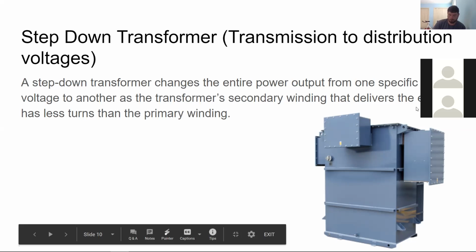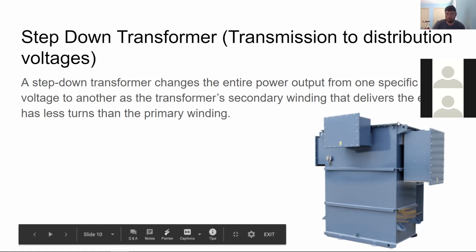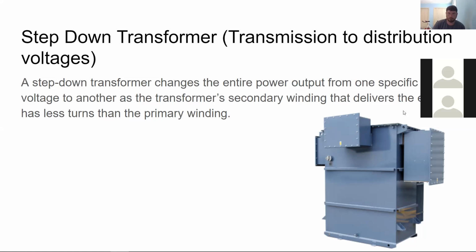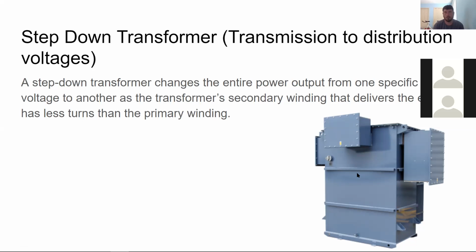Nope. Who said? Looks like a transmission, maybe. To be honest with you, he just caught a picture here of one that's in transit. Substation transformers don't come with any oil in them. They don't come with any bushings on them. You've got to build them at the station. If you put all that stuff on them, it makes it much, much heavier as far as the installation of it. A typical Santee Cooper substation transformer is going to run you right around 120 to 130 tons. So if you're able to limit the amount of weight on the transformer to be able to set it, this is one that just hasn't been built yet.